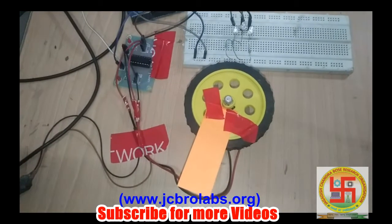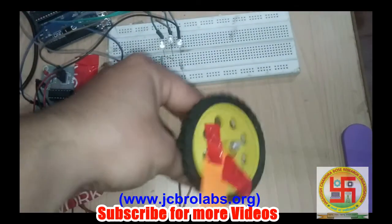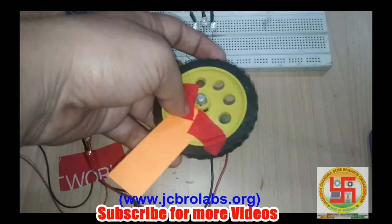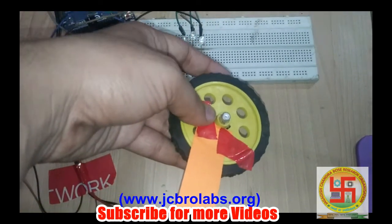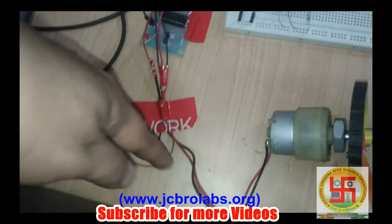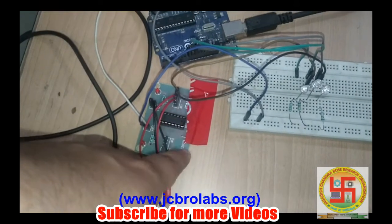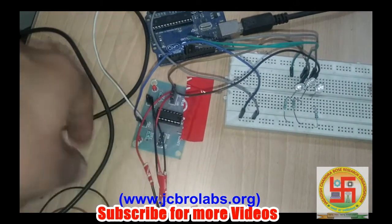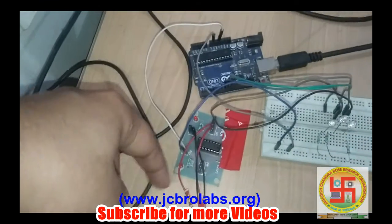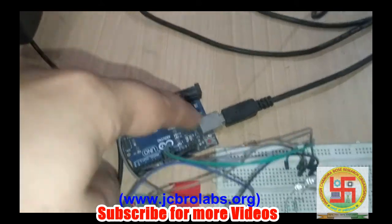So this is our setup. This is our DC motor. We have put red sticky notes in order to visualize the direction of rotation of this DC motor, and it is connected to this motor driver IC. This is L298, so this is a complete circuit, and we are providing 12 volt power from this adapter to this, and 5 volt power is being provided from this Arduino UNO.